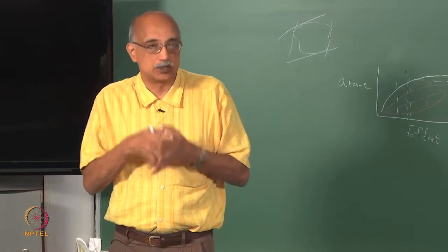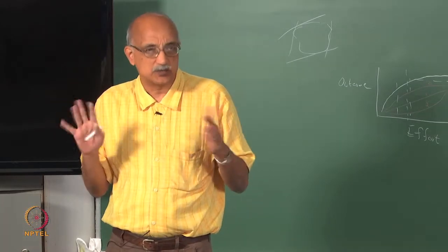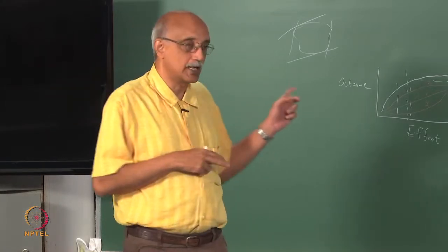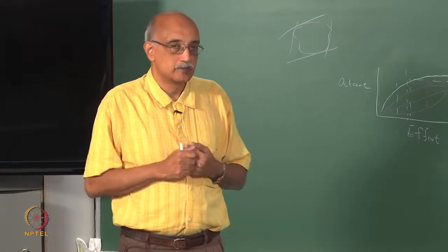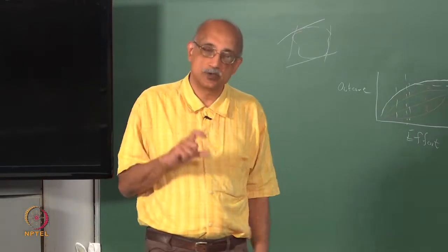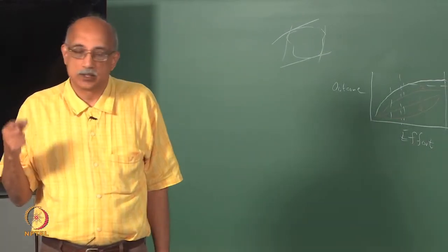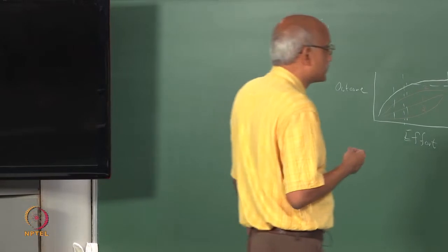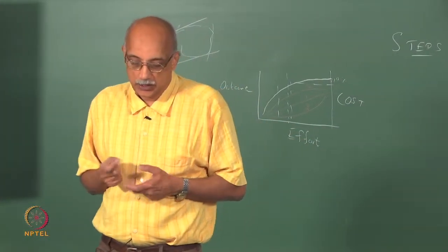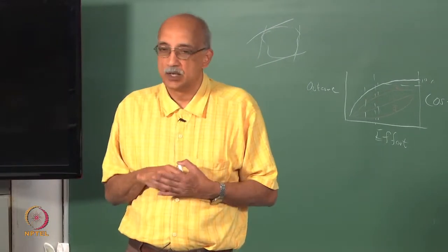You can look at the distribution of these distances, and if they are roughly equal, then you would say it is a spherical particle. But if these distances between tangents are very different, you would say that it is a highly non-spherical particle. So, sphericity can actually be inferred from these measurements, and that can be presented as a qualitative measure of shape.